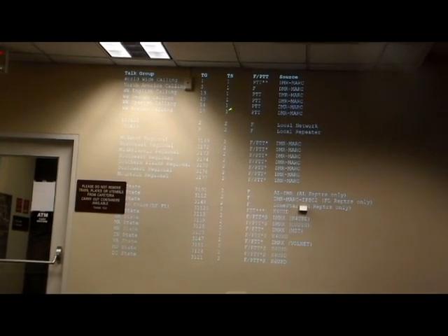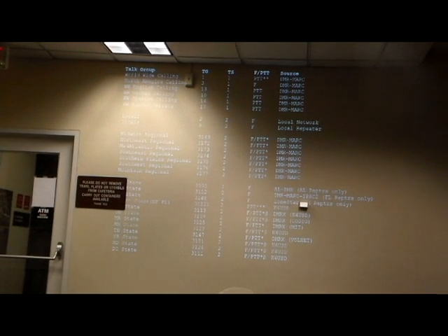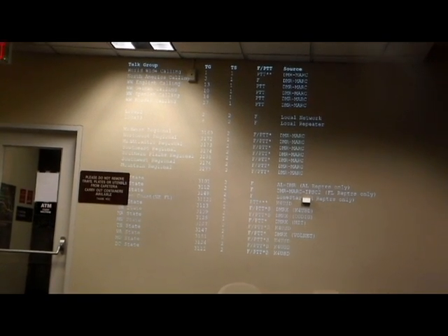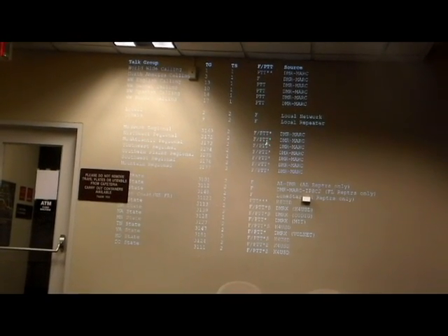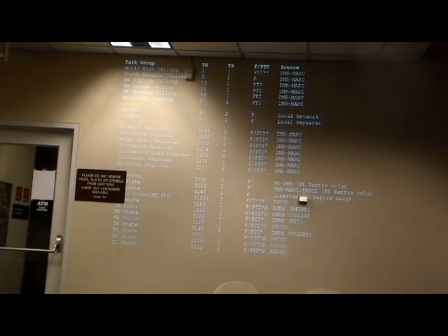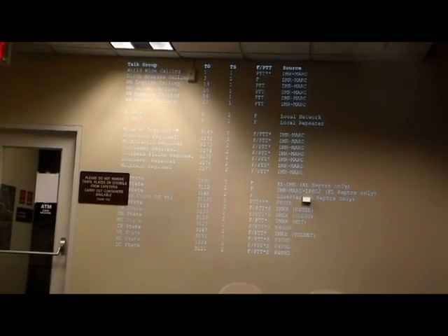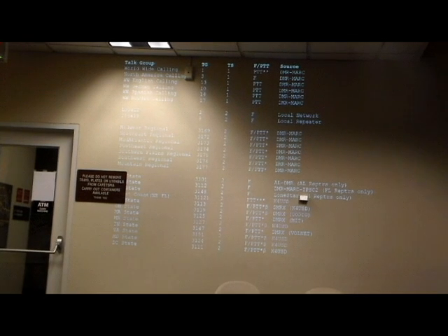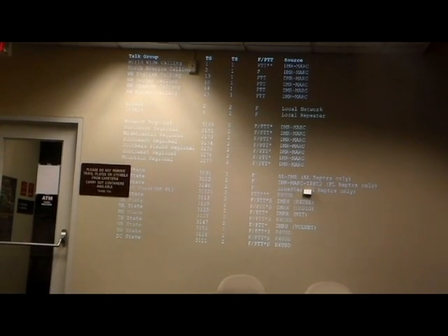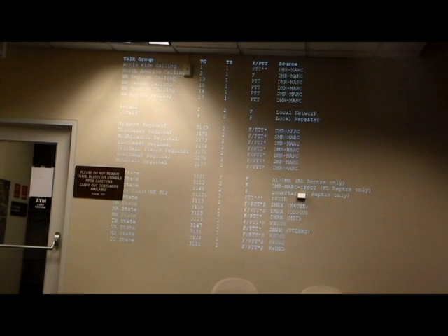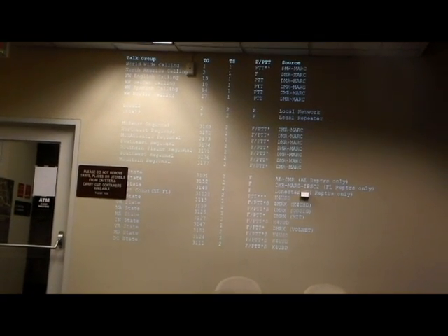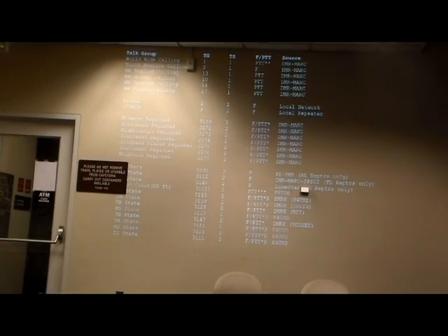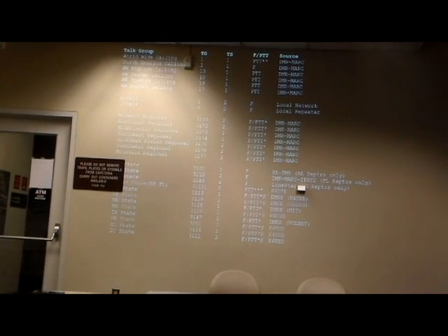These could be linked to any time slot on a different repeater. There are some setups, including Brandmeister, that allow you to link any talk group to any time slot you want. FPTT is whether it's full-time or push-to-talk. For this particular one, generally any region that you're a part of is full-time, and anything else is push-to-talk. When there was the hurricane going up to the coast a couple months ago, everybody was linked into Florida and all the areas around the coast trying to hear what was going on. So generally, all these are available to you. They just may not be turned on by default.